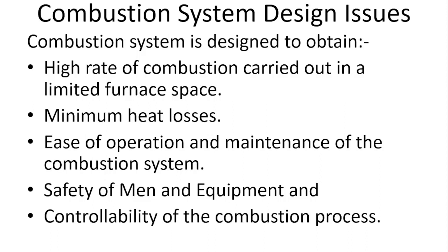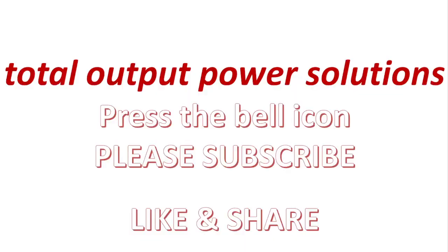Combustion system design. What are the issues? Combustion system is designed to obtain high rate of combustion carried out in a limited furnace space, minimum heat losses, then ease of operation and maintenance of the combustion system, the safety of men and equipment, and controllability of the combustion process.